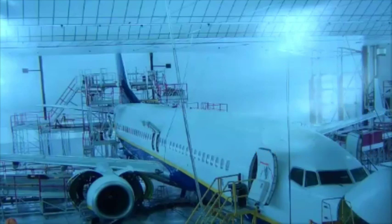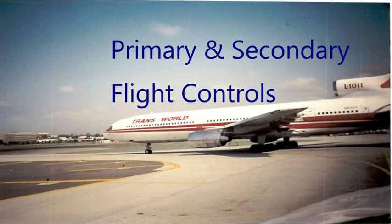Here you can break this up into 2 different types. You don't have to, but it's just a way to compartmentalize the information. You have primary flight control surface devices. You also have your secondary. And what differentiates those 2? Basically, primary flight controls are essential for keeping the plane in the attitude that it needs to be, basically flying the plane. The secondary flight controls are there to fine-tune the performance of the attitude of the airplane.